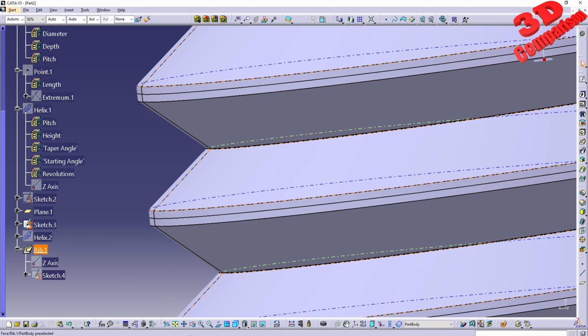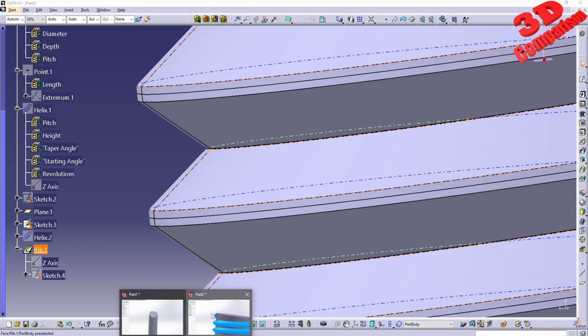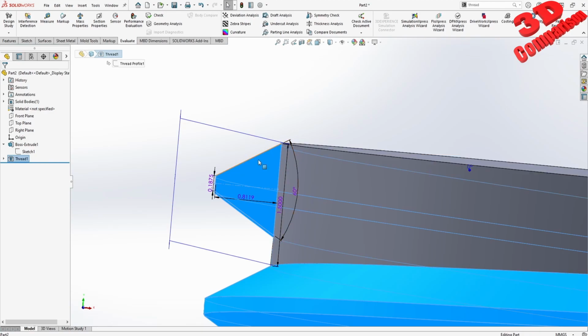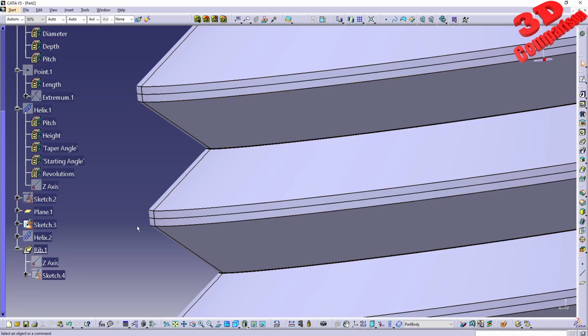undercut, so maybe the location of this profile, as we can see over here, this is 1.5. Yeah, now I see what's the problem. So this is a distance not for that segment, it's for the whole pitch. Yeah, because that's why it has a 1.5 pitch. So let's just add the 60 value over here for those, and that should auto fix this.